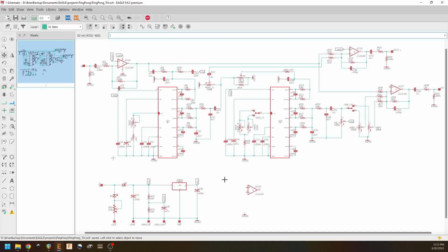So there we have it. We've now got our full schematic, and we have also identified some things that we want to play with on the breadboard. For example, we want to play with the signal attenuation level between delay stages 1 and 2. We want to look into some of the specific component values. We also want to look into adding an LFO or some other kind of modulation onto our delay time to see what we really want our pedal to end up being.